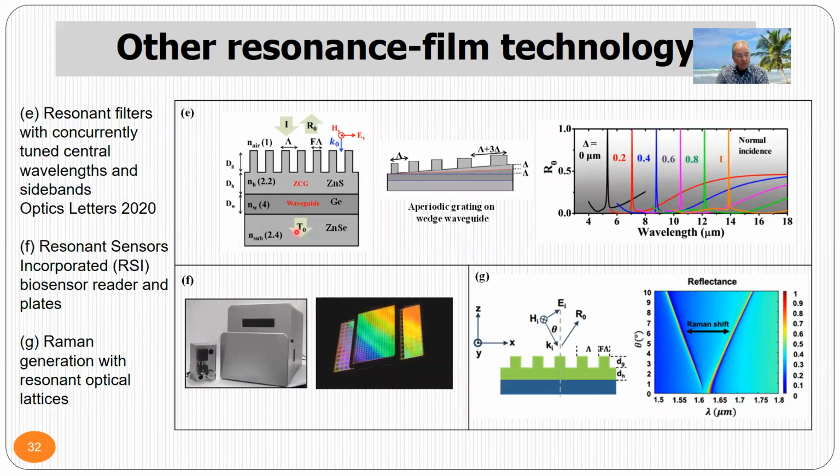And we also designed and actually fabricated tunable filters where we vary the period. If the period is approximately constant locally, there is still resonance. And so by judiciously varying the period, we can actually tune the resonance wavelength.